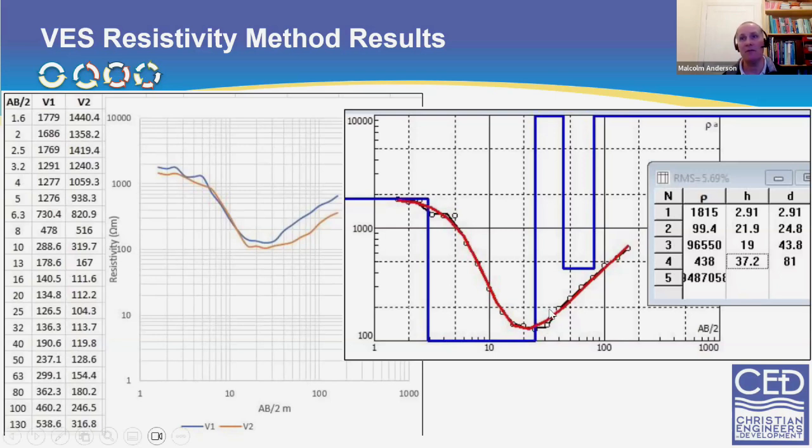So this next zone between 25 meters and 80 meters is a fractured or variably weathered component. So what it's telling us is that a borehole in this location should be quite good, because we would expect to get a fairly productive water supply from 25 meters to 80 meters, which is the main productive zone of a 100-meter well. So that's a good result.